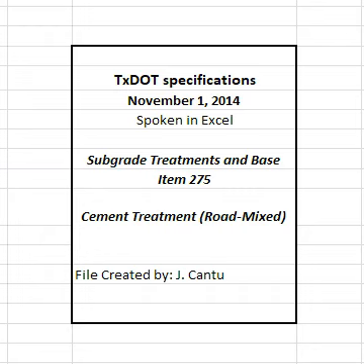Stockpile as directed. The engineer will test the borrow source and determine the sulfate and organic contents. When the borrow source has a sulfate content greater than 3000 ppm or an organic content greater than 1%, proceed as directed. When new base is required to be mixed with existing base, deliver, place, and spread the new material in the required amount per station. Manipulate and thoroughly mix new base with existing material to provide a uniform mixture to the specified depth before shaping.